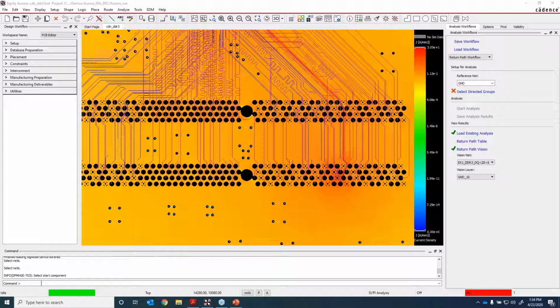Our first question, Jerry, is for the impedance analysis: is the tool assuming the reference plane is the adjacent layer, or can you define it as something else? By default, it assumes whatever is the closest plane that's classified as a reference. Any kind of ground has essentially a classification or a 0-volt value in terms of the PCB editor's classification.